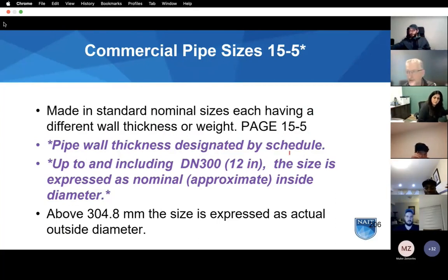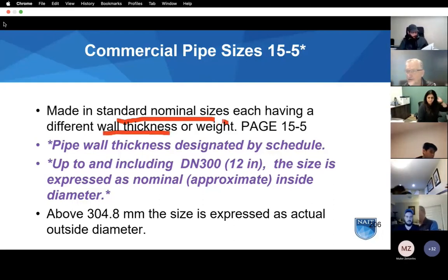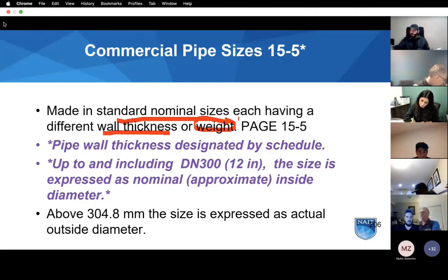So if you carefully have a look at that chart, you're going to see that there's different sizes and different thicknesses. And pretty important to remember, there's weight in the chart. There's 2 numbers in many of the squares on the chart, and there's a note. Upper figures are wall thickness in millimeters. Lower figures are mass per meter in kilograms.